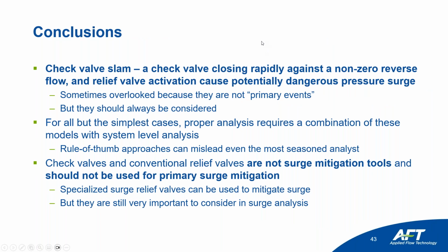So in order to conclude, going back to what Scott had said, we're interested in simulating check valve slam with regards to systems level design, check valves closing rapidly against a non-zero flow, and we're also interested, from the relief valve side, in relief valve activations that cause potentially dangerous pressure surges or exacerbate the effects that we would see. A lot of times these are overlooked because they're not primary events. Usually they are passive devices or passive transient devices that aren't accounted for.